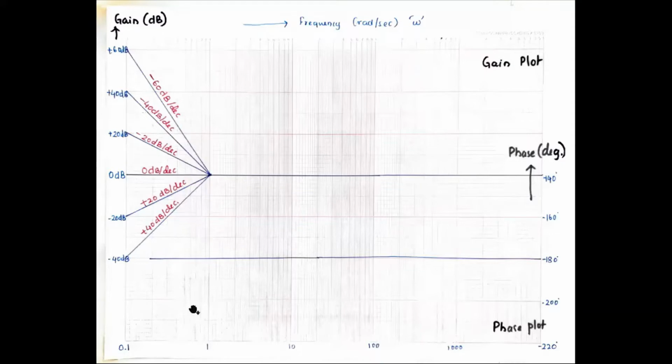So this is how it looks. This is called the x-axis, and it is for representing the frequency in radians per second. Okay, the frequency omega. So while drawing, make sure that there is a count written on the semi-log sheet as 1, 2, 3, 4 up to 10, then 10, 1, 2, 3, 4 up to 10. So it's been printed there, but we have to use that scale such that each solid line represents a decade change, or a change of 10 times in the frequency. So this is the first solid line. I will choose this first value as 0.1 radians per second.